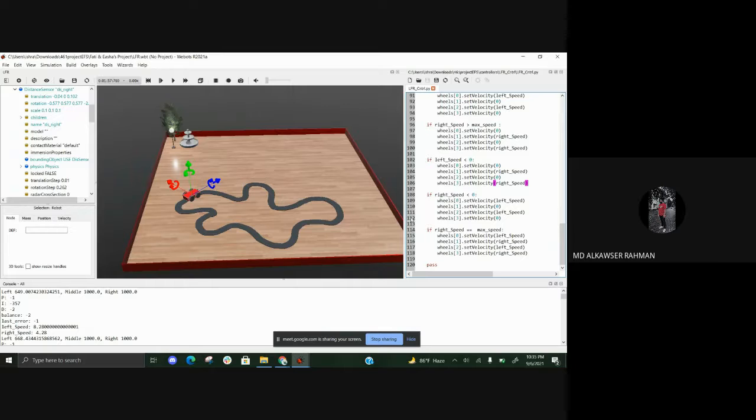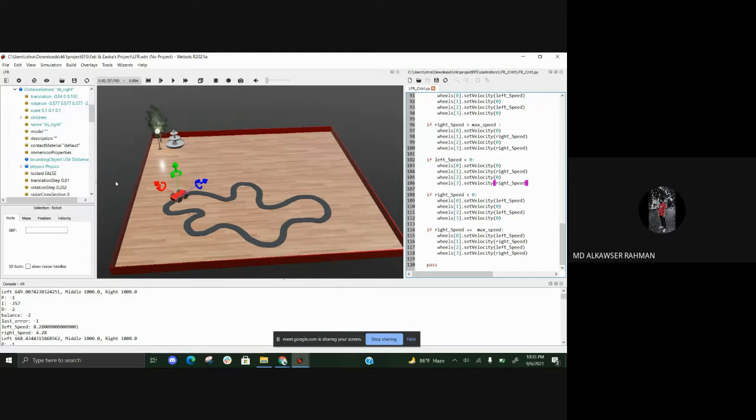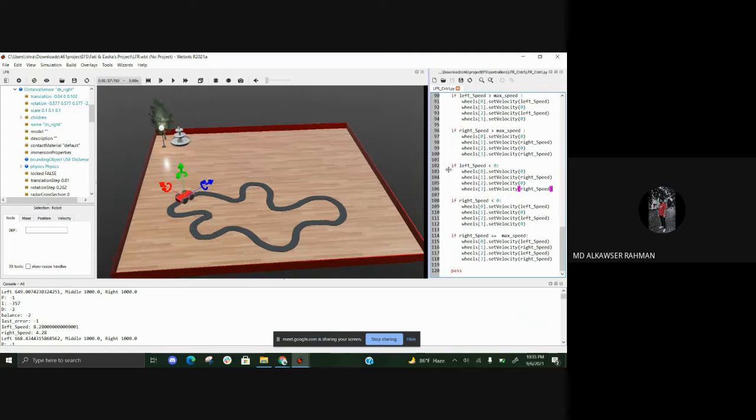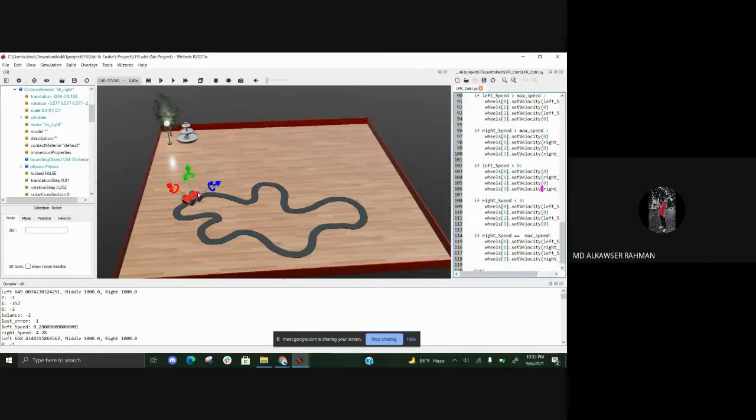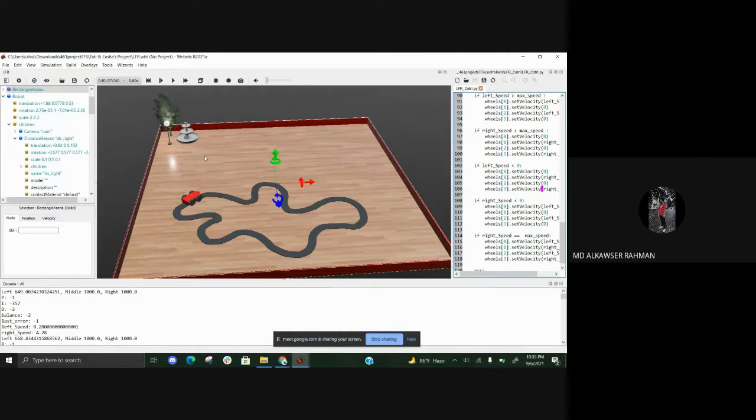Firstly, let's start by summarizing our line follower robot project quickly, and then we will simulate the project for better understanding, where we will be able to see how our robot performs by moving around the track and following the line without getting interrupted. As mentioned earlier, we have programmed this particular robot with the proportional integral derivative, or PID, control system, which makes it possible for the robot to follow a track by generating a control loop feedback using the data from the sensor in order to stay in line with the path.